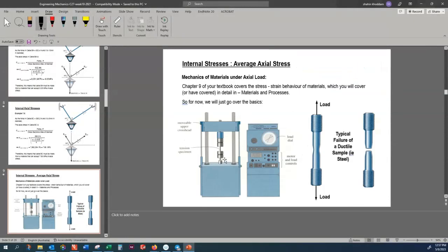That test would show you the limit of the material. The test is called tensile test. Tensile test is a very common test that is done inside most of the structural mechanics laboratories. In that, you have to make a standard sample out of the material. Most of the cases, metal, plastic, or even wood.